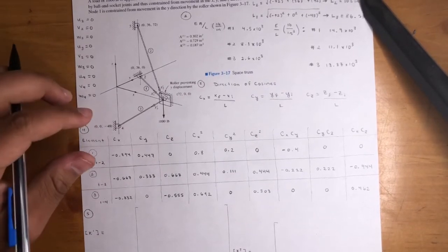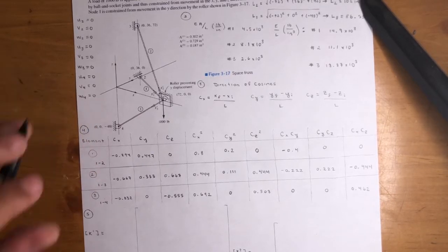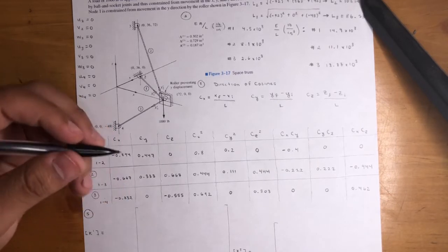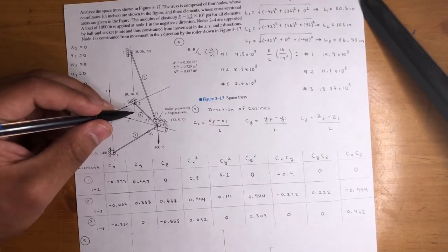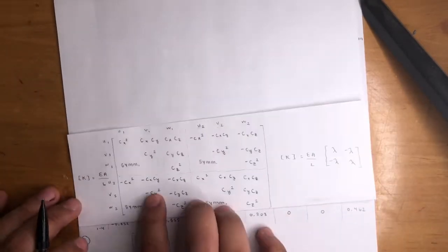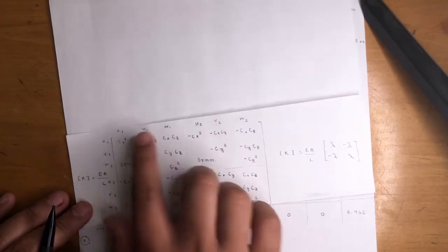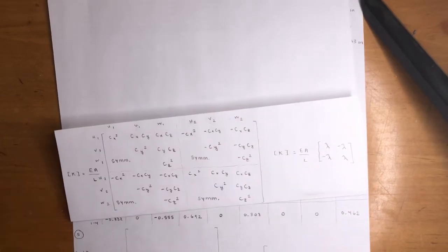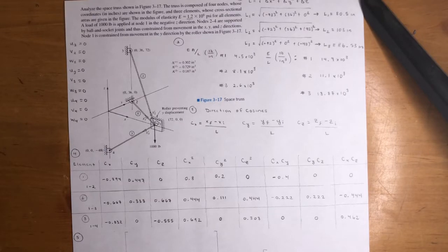Now we're gonna start assembling the little matrices. I forgot the name of it, but the little matrix per element, so later we could get the global stiffness matrix. So let's go ahead and do that. K1 for element 1, the stiffness, we're following this formula. It's K1 is equal to EA over L of that element, and then between whatever nodes it's in, and then just fill in the values. That's all we're doing. So that's the formula right there if you want to screenshot it. And then I'm gonna remove it, just FYI.